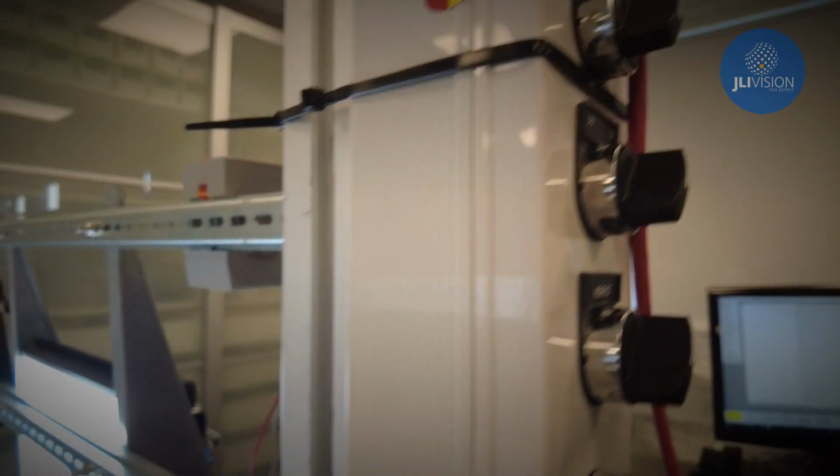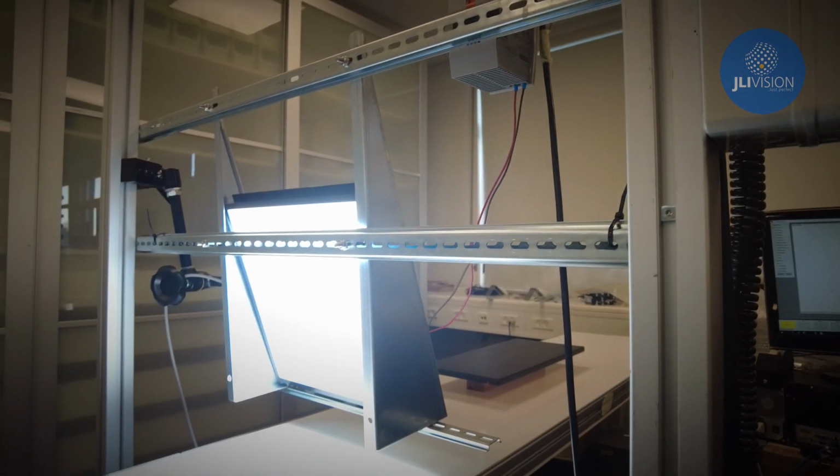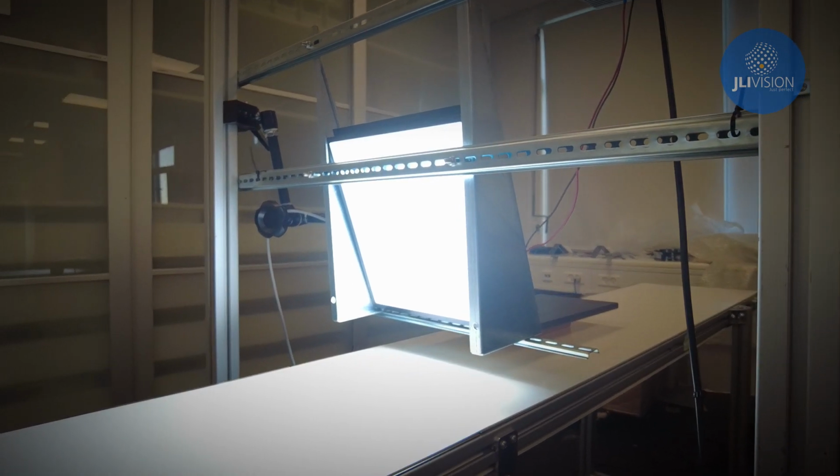An additional challenge of this process could be that the object we're actually looking at has different thickness. And when we have different thickness, the way the light is reflected often changes. To counteract this, we normally use an actuator, which allows the camera to move to fit the angle of the object we're looking at, and thereby always fitting the right system to the right defect. This process will be done automatically. We will predefine some thicknesses and predefine some positions for the camera to fit those thicknesses.